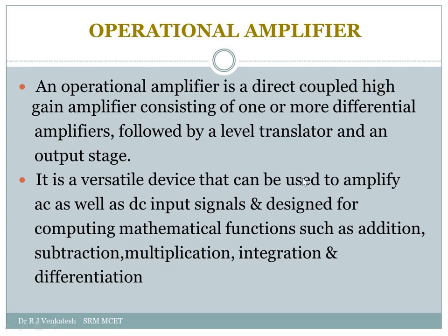First, what is an operational amplifier? Shortly it is called an op-amp. An operational amplifier is a direct coupled high gain amplifier consisting of one or more differential amplifiers followed by a level translator and an output stage.